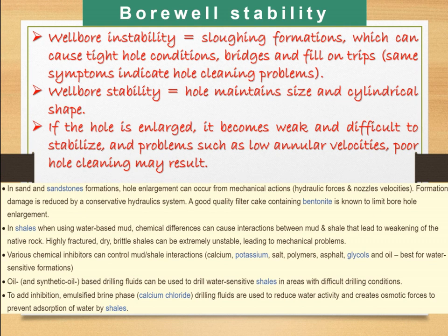Okay. So another thing is that oil or synthetic oil-based drilling fluids can be used to drill water-sensitive shales. Sometimes in areas with difficult drilling conditions, some shales are often water-sensitive. They can show volume changes on interaction with water. So in those cases, oil-based drilling fluids are used. However, oil-based are relatively costlier. To add inhibition, emulsified brine phase calcium chloride drilling fluids are used.